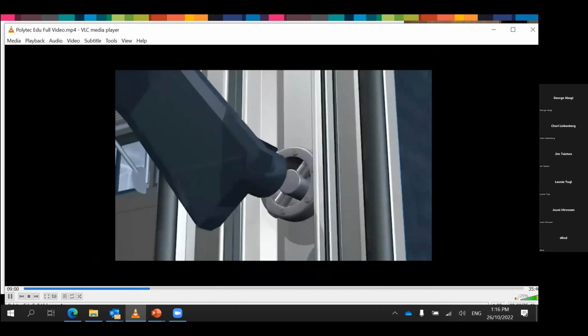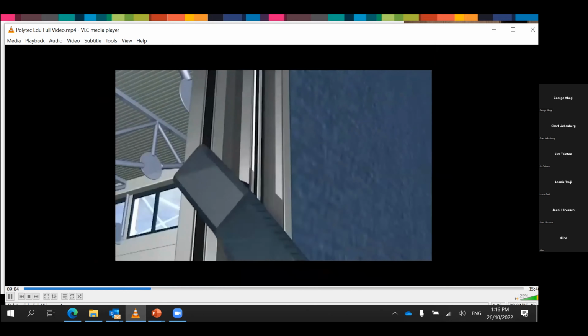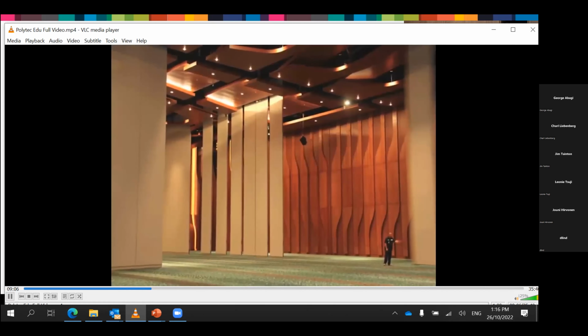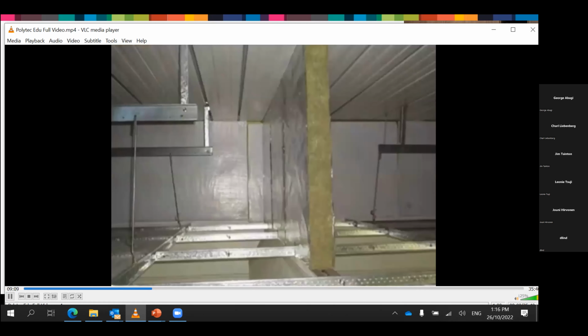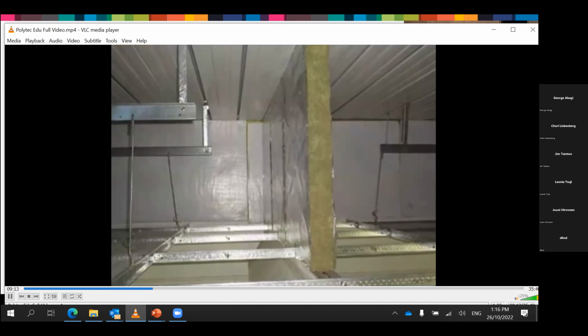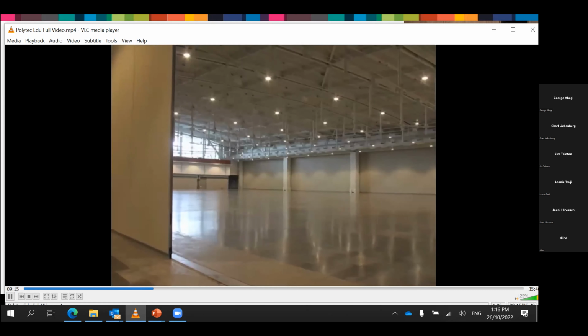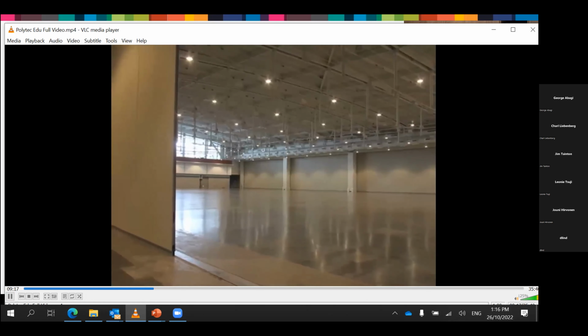When a plenum barrier is used, the sound blocking performance of the wall or door increases. When positioned above interior partitions that stop at the height of the suspended acoustic ceiling, a plenum barrier board stops noise and speech from travelling between rooms through the plenum above the ceiling.